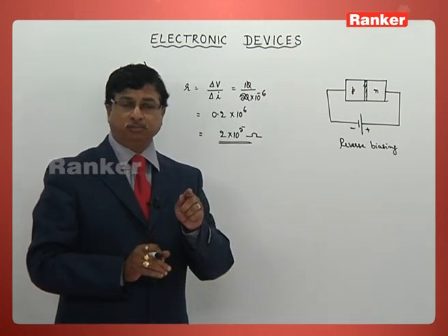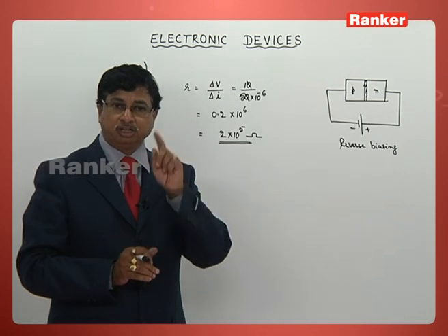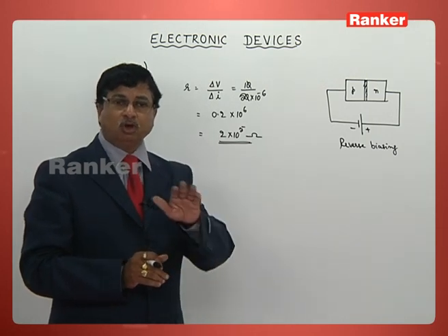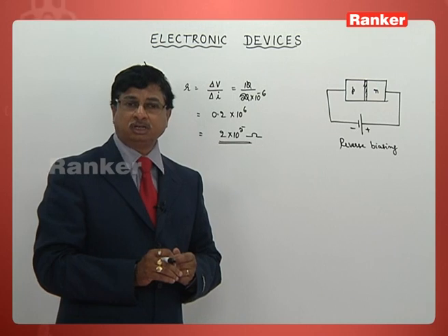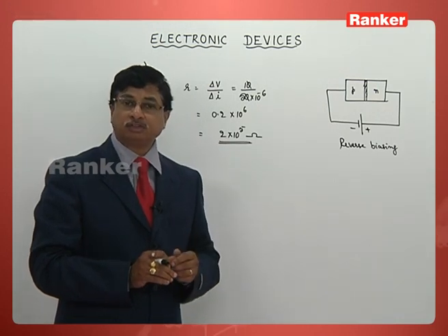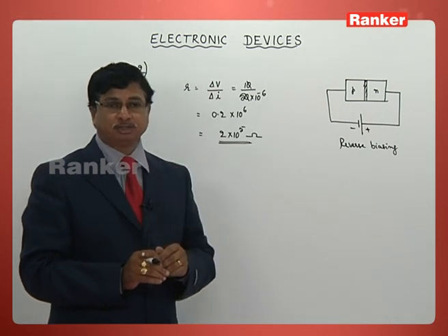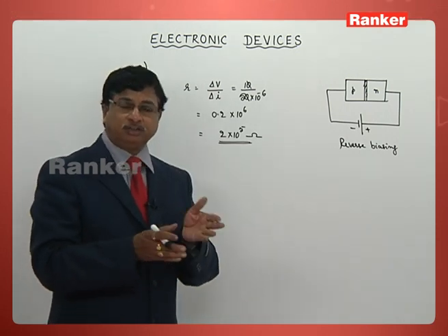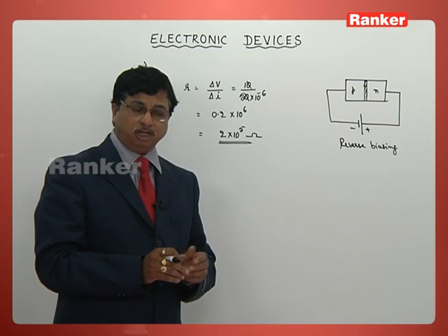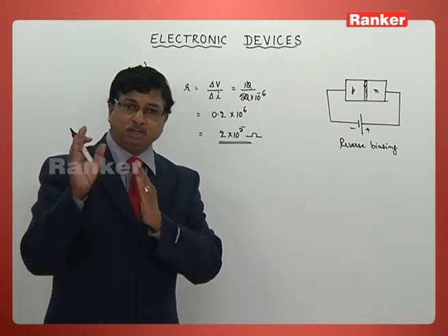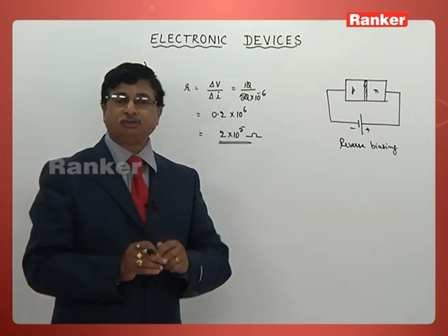Resistance is going to be infinity. That means no current is going to be observed across a PN junction diode in such case. Suppose if it is in forward biasing, the resistance is almost 0. Thereby current increases enormously in that case. That is the difference you need to understand.